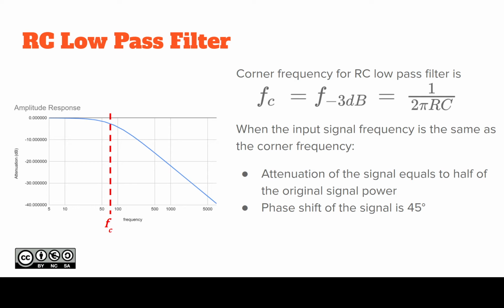And the corner frequency, or basically minus 3 dB, is not just randomly selected. Okay, let's decide that minus 3 dB sounds like a good place to put this corner frequency value, since it fits the numbers. No, it was actually selected the other way around. It's selected so that half of the signal power is left there, which happens at the phase shift of signal 45 degrees in this case. Good.